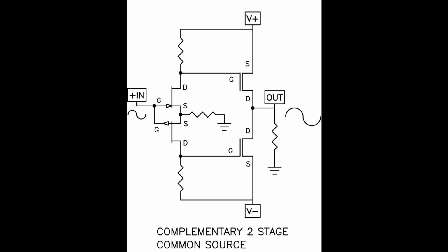We are going to fix those limitations by adding a symmetrically inverted copy of this circuit, where the polarities of all the devices are the opposites. On the top, we have the previous circuit with an N-channel input JFET and a P-channel MOSFET, second stage, and below we have a P-channel input JFET and an N-channel MOSFET. These two halves will operate in a push-pull fashion and greatly increase the output power and also cancel much of the distortion.